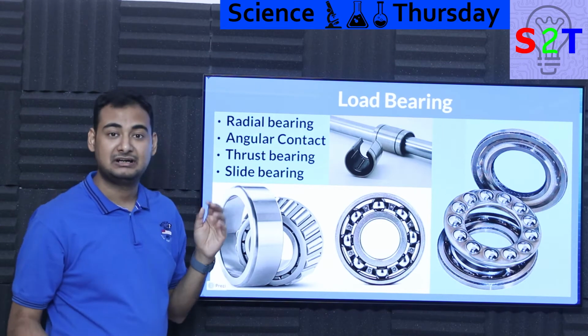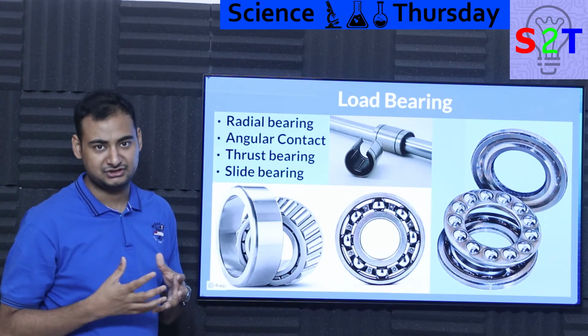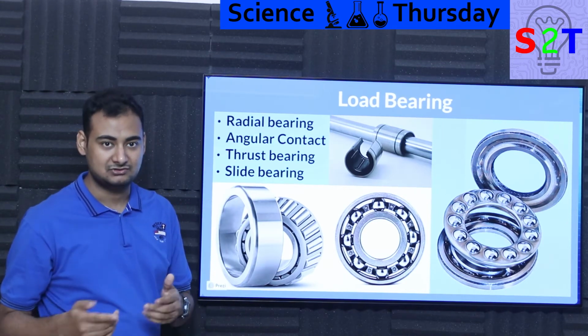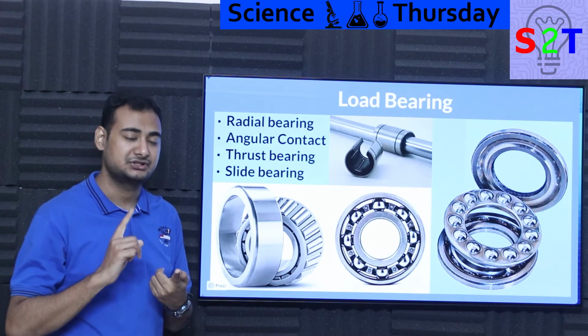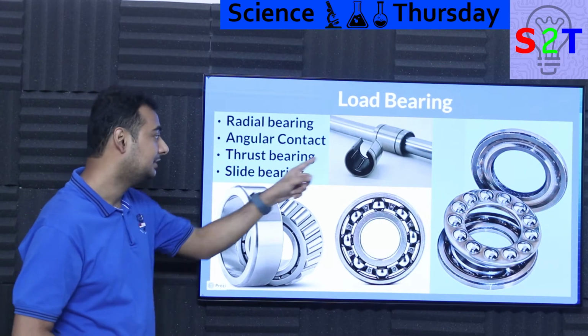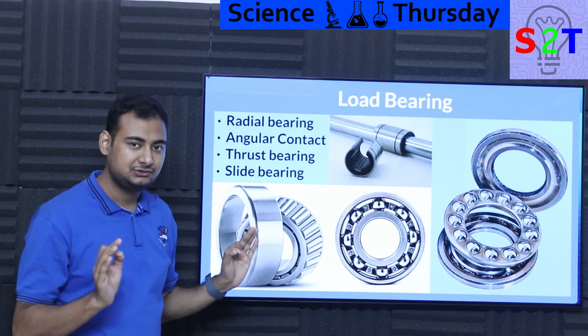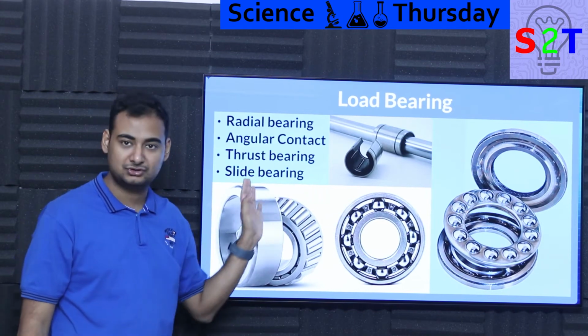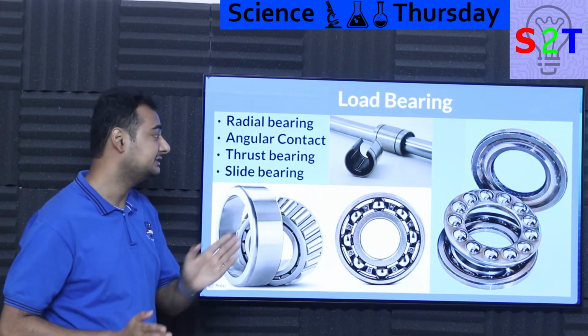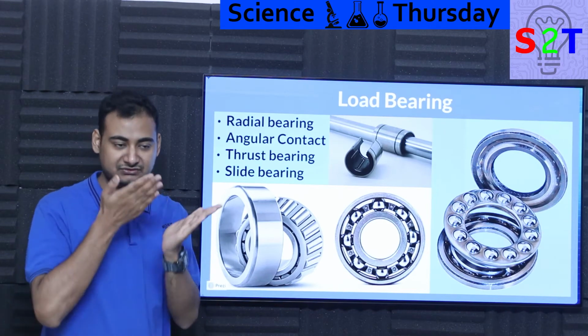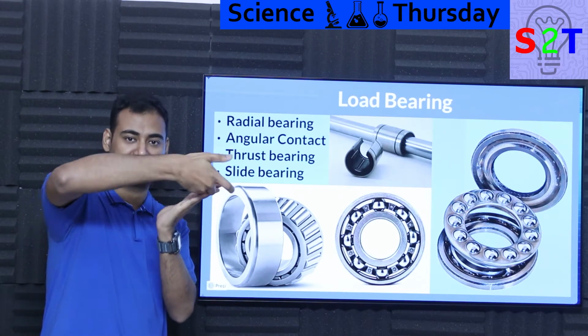And then you have slider bearings, generally used for CNC machines, so basically computer numeric controls, be it 3D printer, be it CNC milling machine, be it lathe or whatever have you. So all you are trying to do is make sure no matter what happens, whatever the motion system is, whatever the axis of motion is, you never have sliding elements. You never want this to happen. You always want rolling elements.